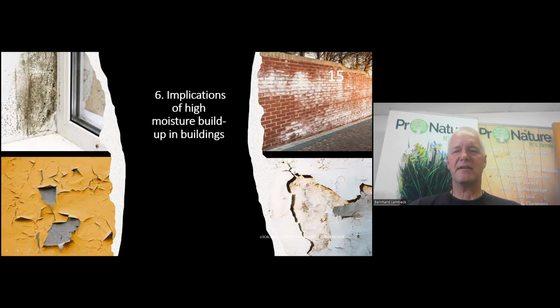So I reflected on crumbling plaster, the efflorescence, and paint that simply peels off because there is too much moisture trapped behind the paint film, and those paints were not designed to allow for a release of the moisture that is trapped within the wall.